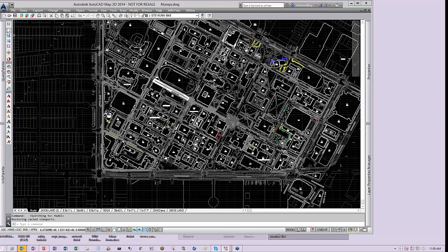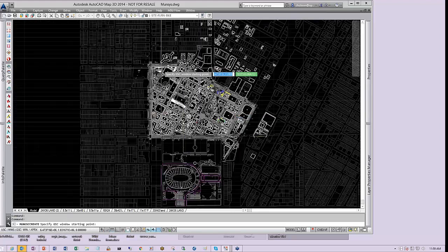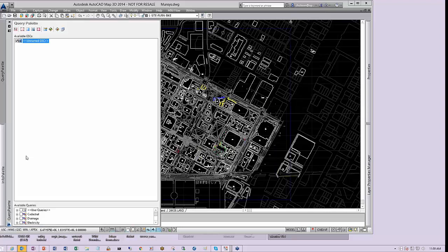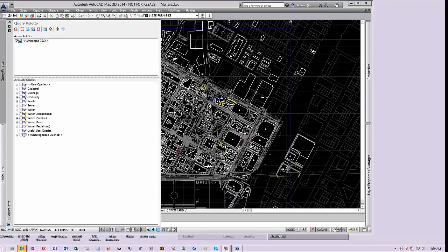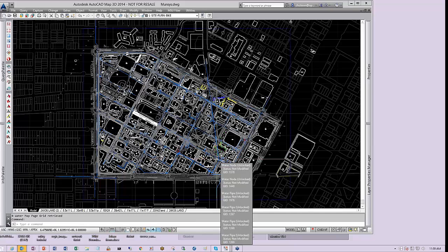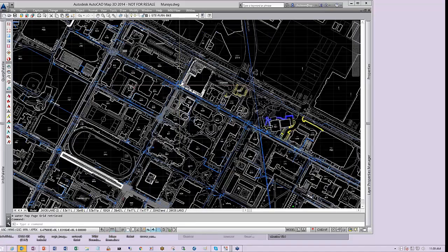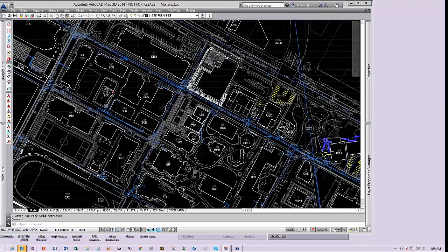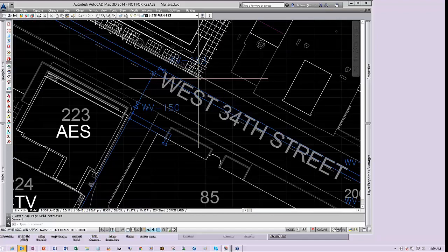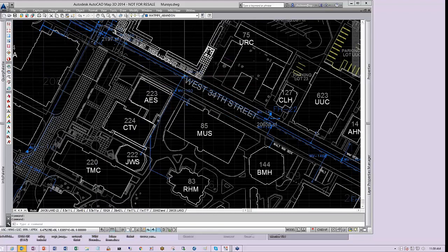So in here we can come in to this, and let's say we're interested in that area there. I can come in and then say, well, let's use the GIS tools to zoom to, say, all the water in that area. And so this is sort of where that CAD drawing has been processed. In other words, taken and turned into the little lines, polylines and everything, turned into blocks and attributed, and the lines being segmentized so that if I click on a line here, you'll see it goes from that valve to that valve, and everything has been done like that.